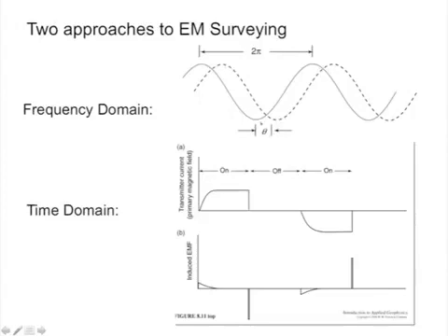Okay, so here this phase difference looks like 1/7 or 1/6 of the circle, so it would be 60 degrees out of phase. Okay, and that's due to this sinusoidally changing magnetic field inducing sinusoidally changing eddy currents within the ground, according to Lenz's law.